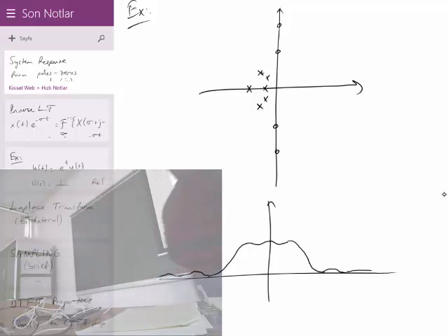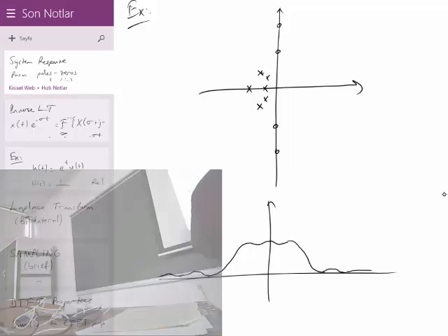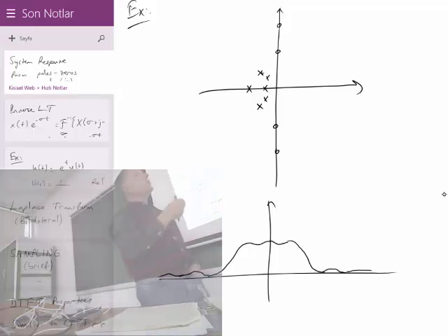And here I observe a peak. What can that peak be? That peak is a frequency value somewhere here, which is nearer to a pole. As you become nearer to a pole, the distance, for example from here to here, will become small and it's in the denominator. So a small distance in a denominator will make the amplitude larger. That's why you observe a peak here. And this frequency here is nearest to this pole, for example. We have another peak here because there is a pole which is nearest in distance to the j omega axis at omega equal to 0.